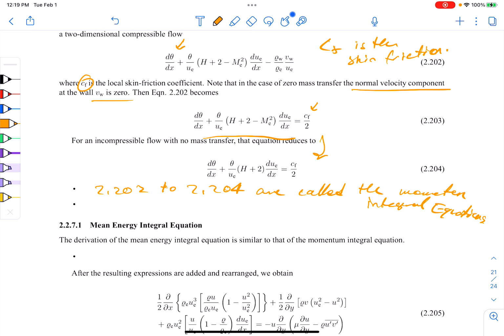Through integration and non-dimensionalization and a little bit of simplification, noting that turbulence goes to 0 at the wall, you now have basically a one-dimensional equation that only involves boundary layer thickness and shape factor, and you can estimate skin friction on an aircraft. So that was a huge advance, and it's an ODE, meaning that for some simple configurations, I can actually estimate skin friction and therefore drag on early vehicles.